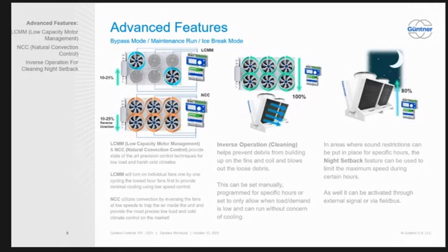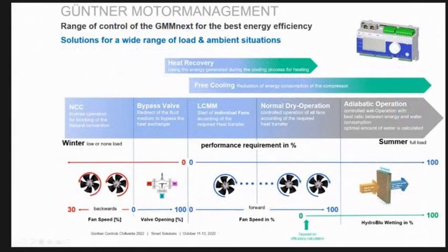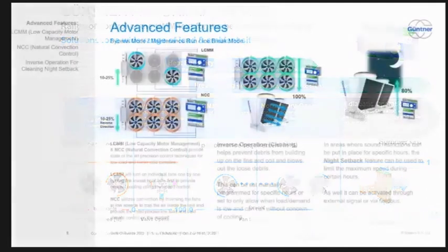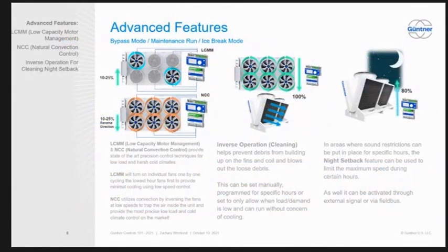So he sends me some pictures of the unit, and apparently the unit was on the Las Vegas Strip, and there was all this nasty debris, like plastic bags and all kinds of things, covering the adiabatic pads. So there was no airflow across the pads. The fans were running at 100%, but it wasn't cooling, and that's why it wasn't cooling.